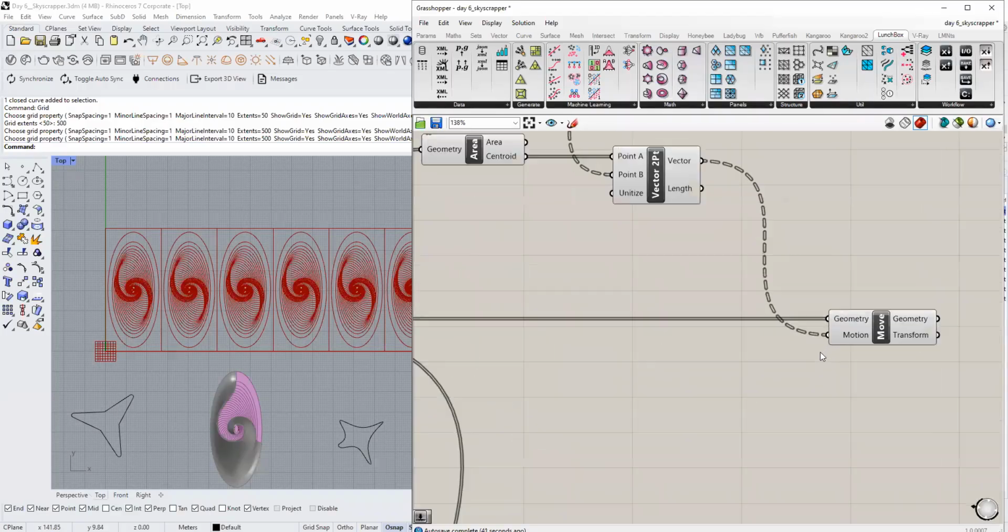You can see that there are components that are involving a list and a tree. We had a similar issue in the previous class when you have two different data structures coming together in a component, and you notice this kind of additional outputs. It means it is something to do with the data structure. Like you have additional outputs or you have wrong overlapping chaotic outputs along with inputs of different data structures. Most likely data structure is the issue.